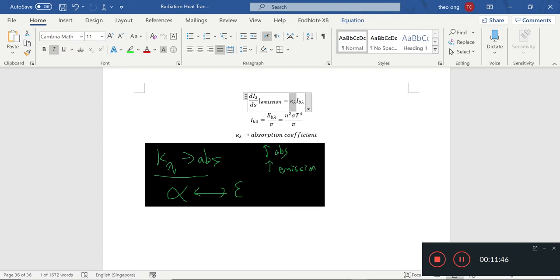That's why it is participating media in the first place, otherwise it'd be a solid black body. The degree to which it behaves like a black body is determined by this absorption coefficient, and that also affects the emission. So that's an intuitive sense as to why this formula works.